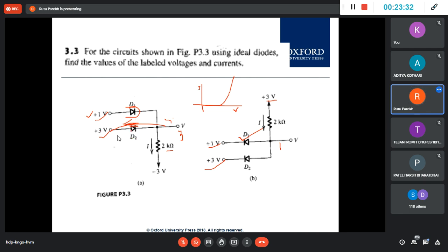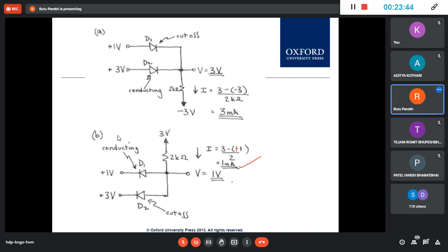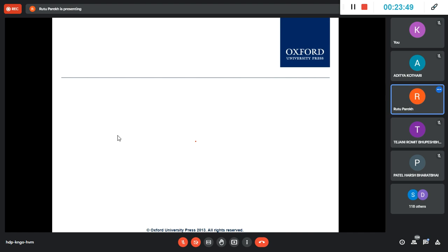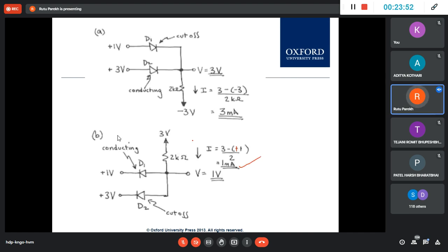Here it was more positive. So this is more forward bias. Okay, that way, simple way. Here this is more forward biased, here this is conducting. So when you see both are conducting, but once this starts conducting little, as I said, the voltage will appear here, this will be short since it is ideal diode, and this will get into cutoff.